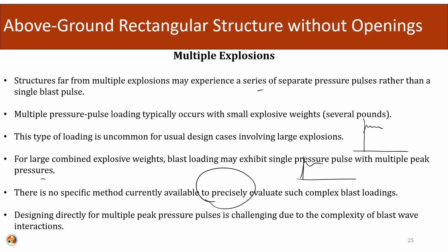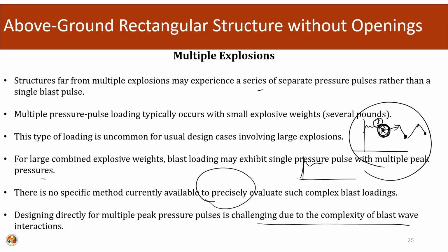we can evaluate the state of stresses during one explosion and keep that state of stress as an end condition. So, the end condition of the first one will be the starting condition for the next evaluation, and we can progress like this in a chain manner. But that itself is also a very tedious task. So, designing directly from multiple peak pressures is challenging due to the complexity of the blast wave interaction.